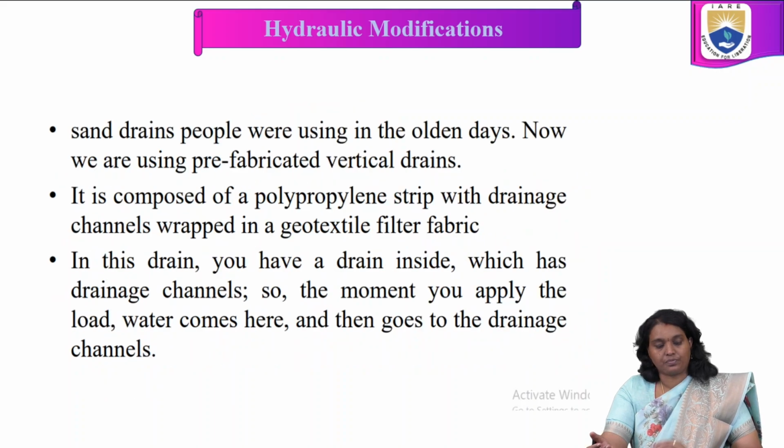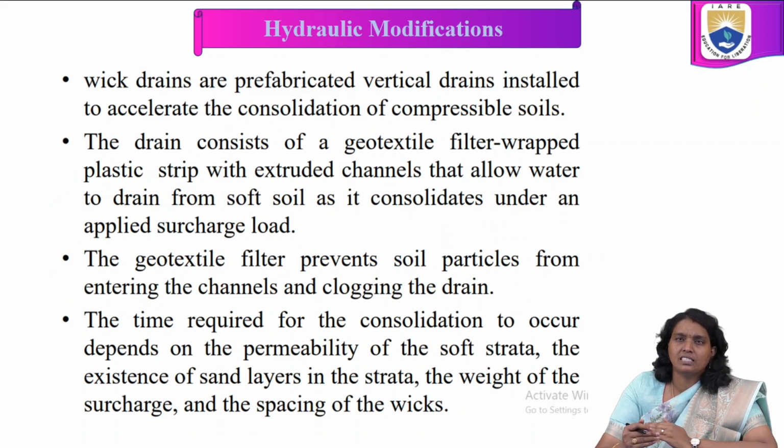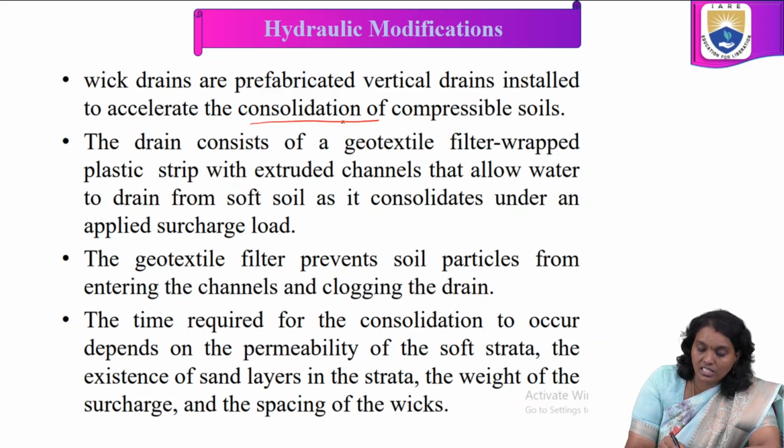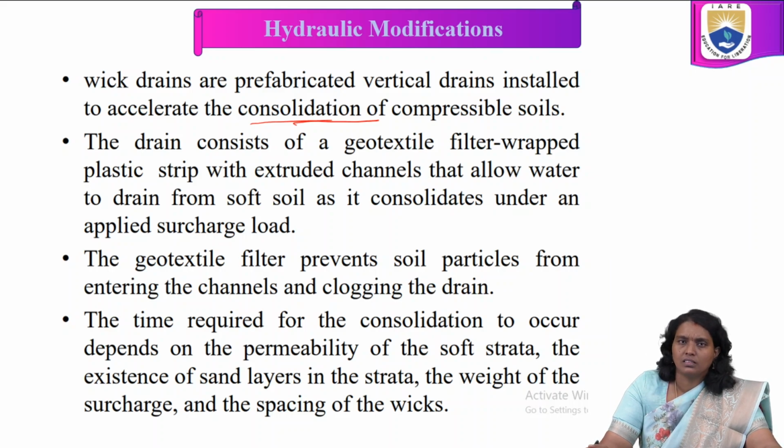Coming to wick drains, they are completely prefabricated. These vertical drains are installed to accelerate the consolidation of compressible soils, helping improve the ground to the desired properties.